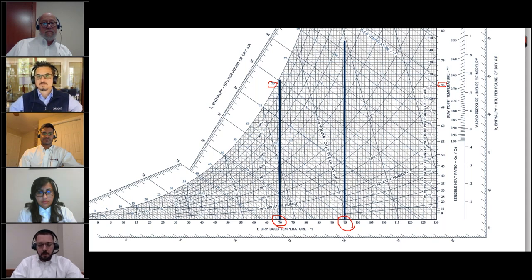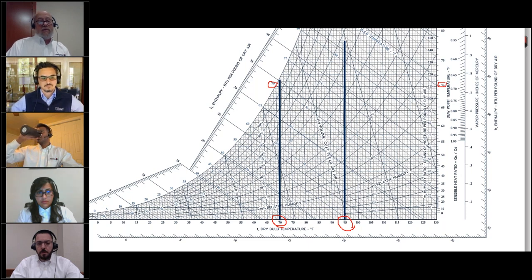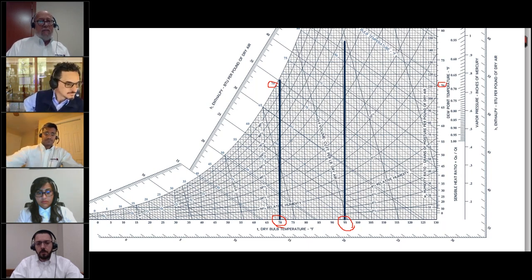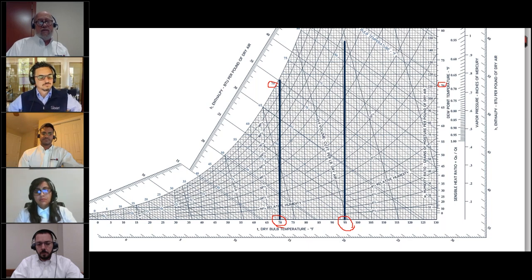Okay, perfect. I think this is just a comment. It's important to mention that standard psychrometric charts are for air at sea level. There are special charts for high altitude. So I don't know if you guys want to comment on that. Yes, very much so. There are different charts out there. Most charts that you have available are based on sea level. As you move up into high altitude conditions, there are high altitude charts out there. There is also another version of a psychrometric chart called a stoichiometric chart, which looks very similar, but is a high temperature version designed for doing flue gas analysis. We apply these same principles to flue gases because understanding the stoichiometric properties of air in flue gas helps us understand why condensing boilers do their thing.